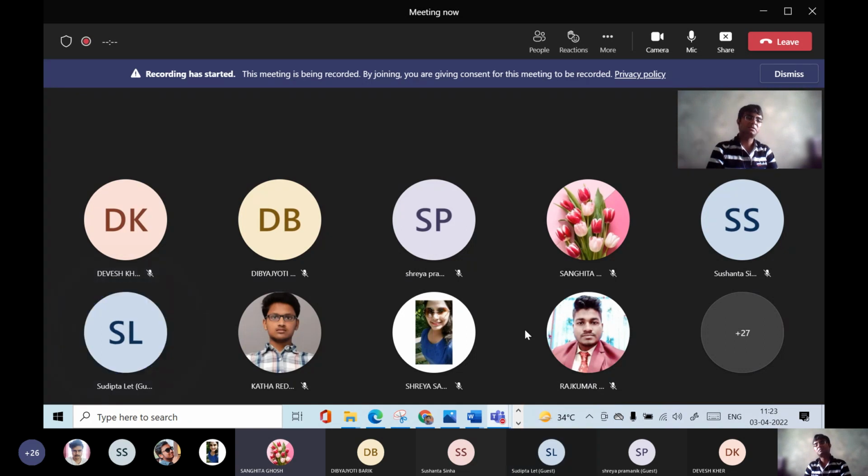No, collection of data is not a problem. In ANSYS 12, you have options. There is a monitor section where you specify what data you'd like to see. If you mention that, at each stage it will show you the pressure, velocity, etc. You will see some graphs moving, going up and down, so you can see it online during the running of the simulation.